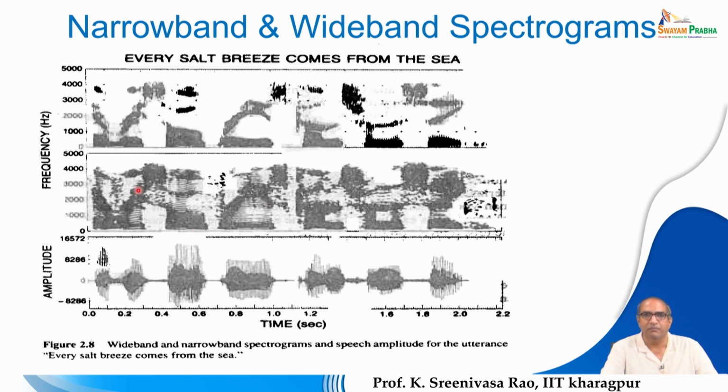But here we are representing that in a two-dimensional plot. That is why you can see this particular spectrogram; there are two spectrograms, I will tell you later. Each spectrogram is plotted on a two-dimensional plot, but it indicates three-dimensional information. One is the time domain information, that is, the temporal information, and the other one is the frequency.